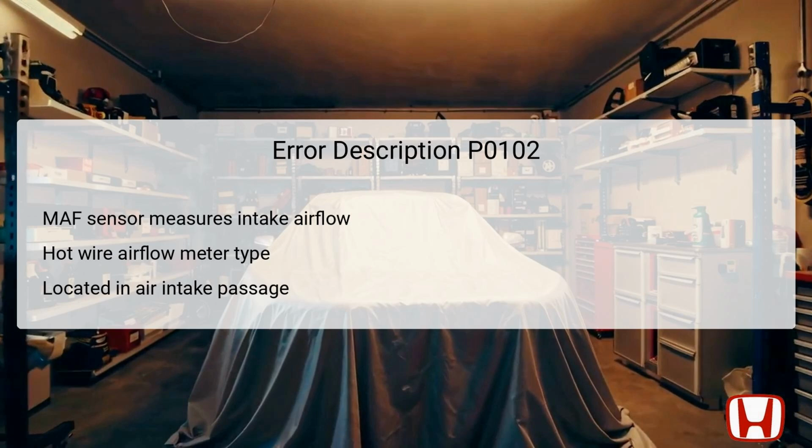The MAF sensor is typically found in the intake air passage just before the throttle body. Its location is strategic. Being positioned in the direct airflow path allows accurate measurements that can significantly influence engine performance. If the voltage output from the sensor drops below 0.10 volts for more than 2 seconds, a fault code P0102 is triggered, indicating a potential issue with the sensor circuit.